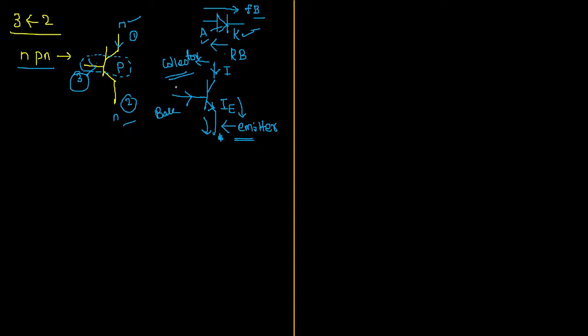Now we are collecting the current through the base and the collector, and then it will be passed through the emitter. Now if you apply KCL, closely observe, we understood that there are three terminals. From the upper terminal, we are collecting a current that is called the collector current. One more current is also being injected through the base, that is called the base current.